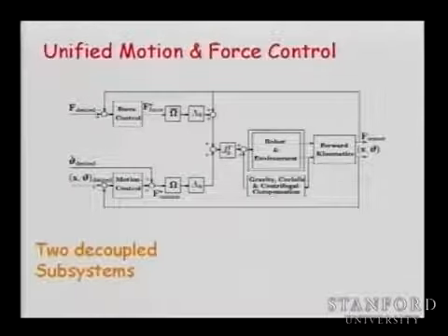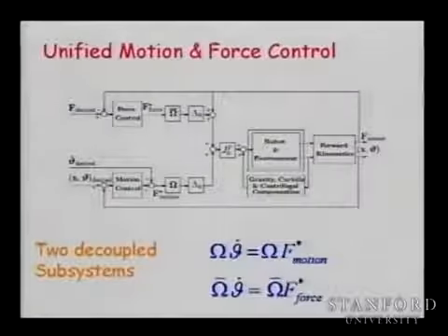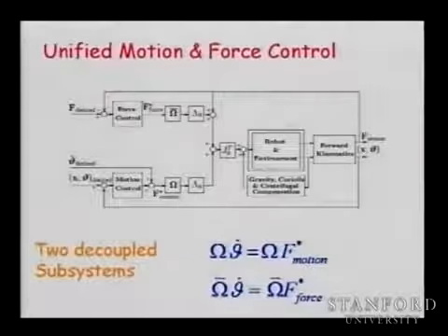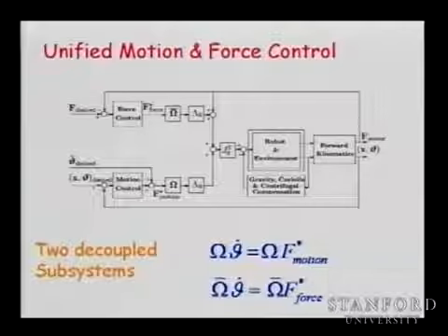The lambda is essentially the mass properties. It is your mass matrix, mx. And this is the mass properties that you are using to scale your controller to decouple the system. And this is done also in the force control loop. The result is very interesting because you can decouple the two systems in their own subspaces. And then you can control them properly.